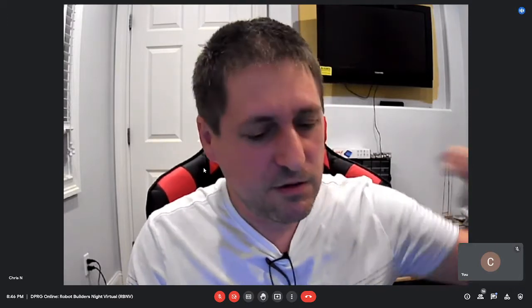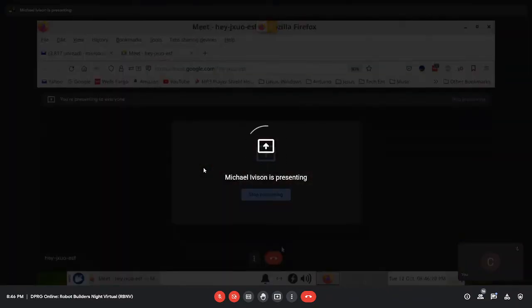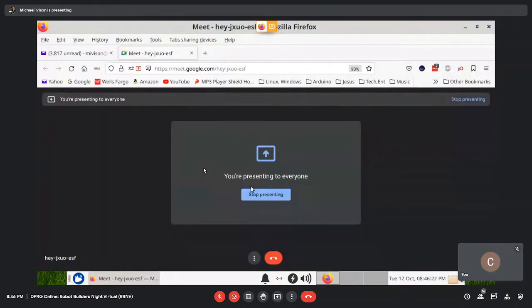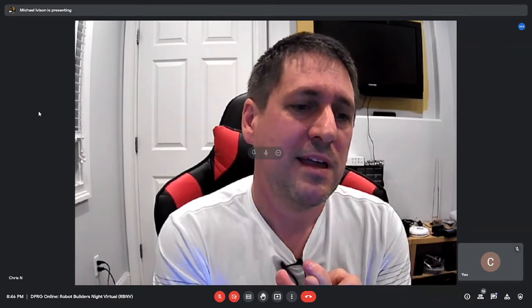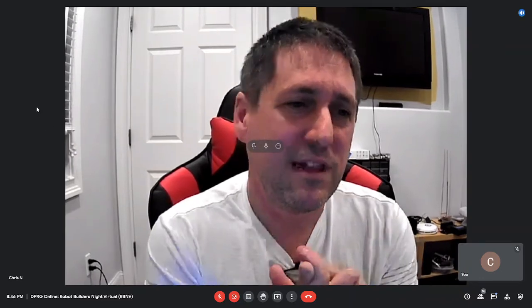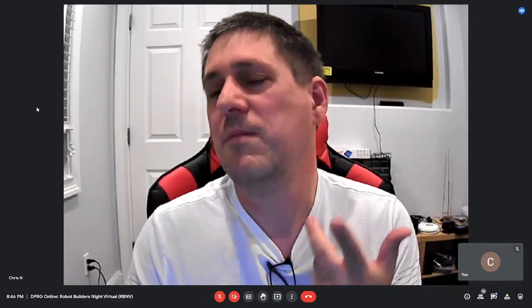And of course, the localization part is a bit more interesting, because that's what helps you deal with the inevitable drift of your odometry and even the IMU, because over time that is going to accumulate some error. So with the localization, and let me start sharing, that's the main reason why I'm looking at some of those SLAM packages from ROS, because to me that's one way.